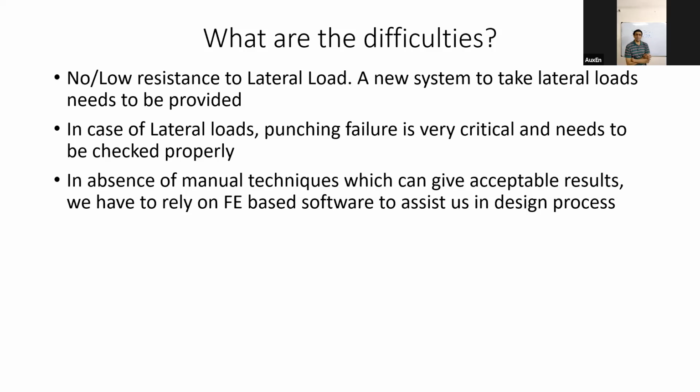Whereas when you are having your normal slab beam column system, the frame system was capable enough of taking lateral loads as well as gravity loads. It in itself was capable of taking both the gravity and lateral. But in case of flat slabs, it is good for taking gravity loads, but it is not able to take lateral loads sufficiently. So you have to introduce another system in the form of shear walls. Is this understood?